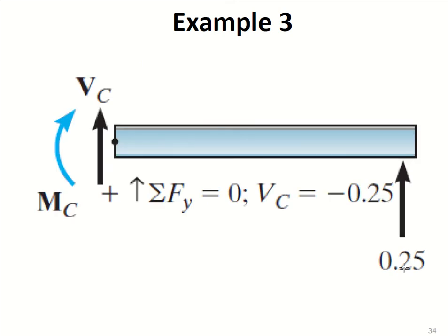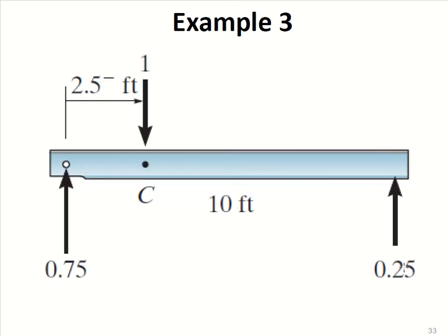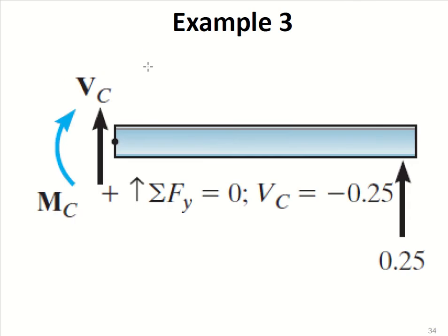Now take any side, either side of the beam. See, for example, the left side or the right side. So if you are taking the right portion of the beam, you know that plus upward shear will be positive. Okay, so there are two conditions when you are taking a section: just to the right of the load, so that the load is not included in the section, and the other is when you are taking just to the left of the load. The section is the same, but in one case you are including the load, and in the other case you are excluding the load.